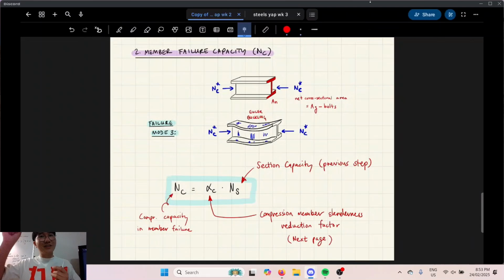So it can buckle locally, and then it causes the Euler buckling to be exaggerated. So you always check for local first. This one's not a matter of preference. For tension design, you can check fast fracture or yielding first, it's up to you. This one you have to do in this order because one's dependent on the other.